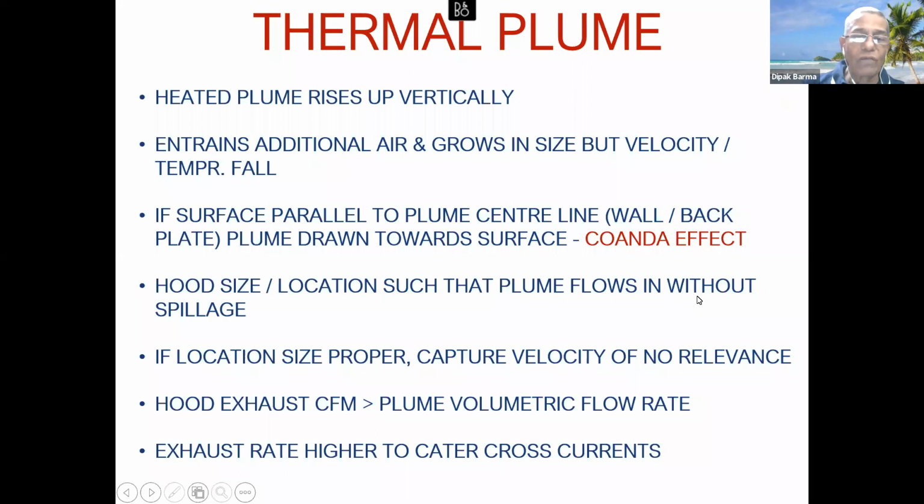Only if the sizing is proper will the capture velocity have relevance. If the size is proper, the entire plume will go into the hood, and if the exhaust CFM is proper, then no plume will flow out from the hood.